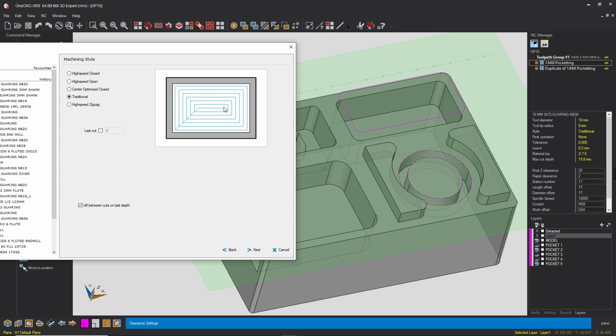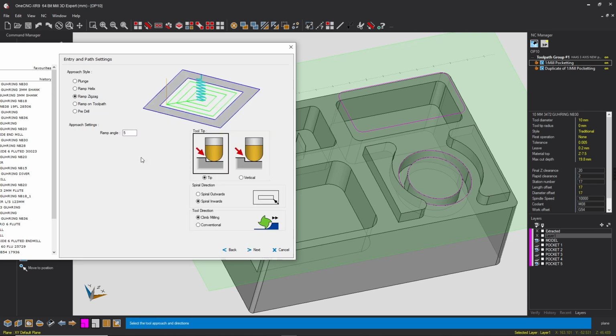But then if you're doing a pocket that's super deep, then you're probably going to find this would be better. If you're doing 50-60 mil deep with a tool that's got the flute to do it, like chip breakers and stuff like that, and you're doing 3 mil step overs at crazy speeds and feeds, that will be faster than traditional. Because you're not going to traditional cut at 60 mil deep, you'll snap your tool. So there are pros and cons for all of them, and you just need to know the best to get the best cycle time, best tool life, etc.